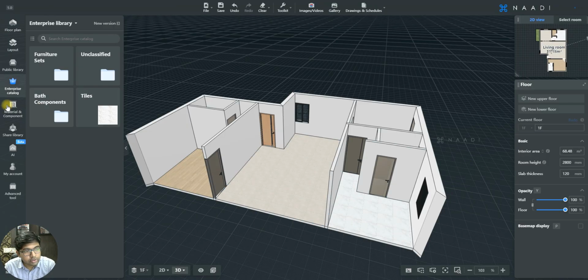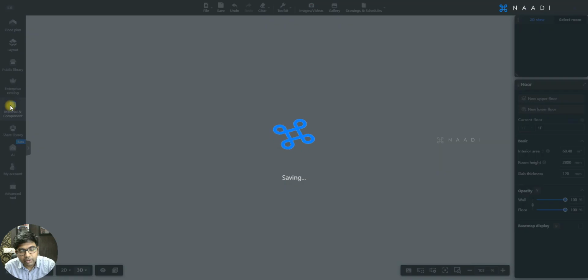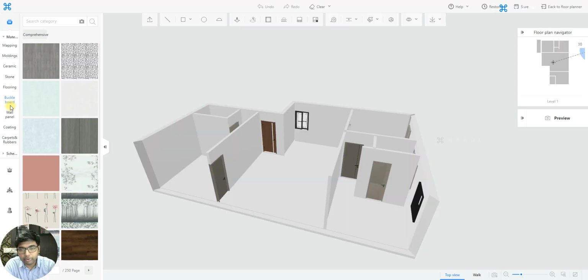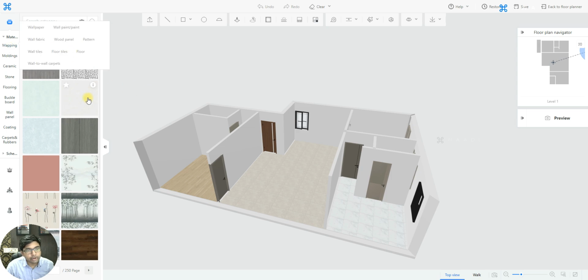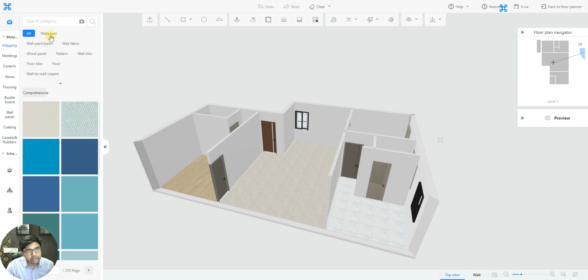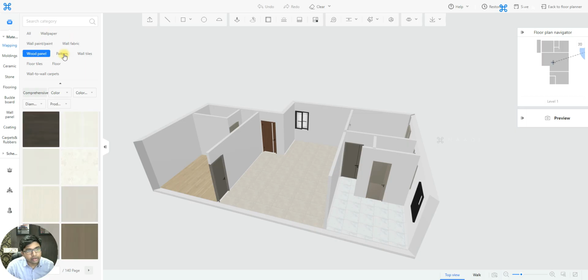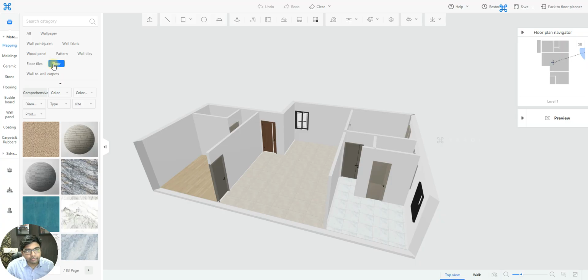you have to go to this materials and component window on the left, click it, and this will open up a separate window named materials and component window. Here you can specifically apply finishes for your masonry structure. In this window on the left, you will notice that you have a public library of materials, where you can precisely select the category and its respective finishes will appear here.